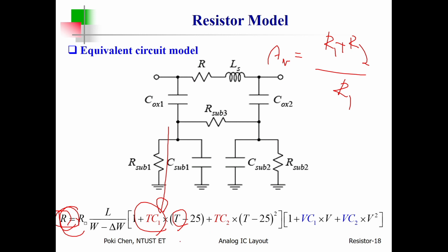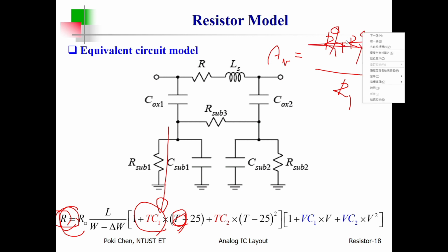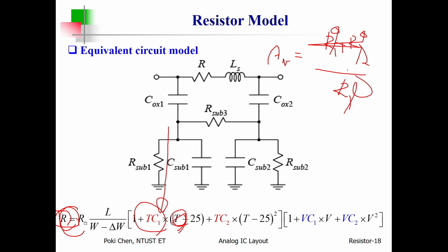Then according to temperature variation, yeah, the resistance of R1 is changed. So does R2. And according to such a relative dependence, don't worry, the final result will be exactly the same. Okay? That is the secret. That is the power of relative resistance. But don't touch absolute. Absolute resistance is no good for your own design.